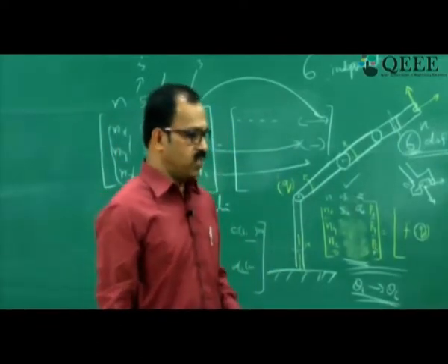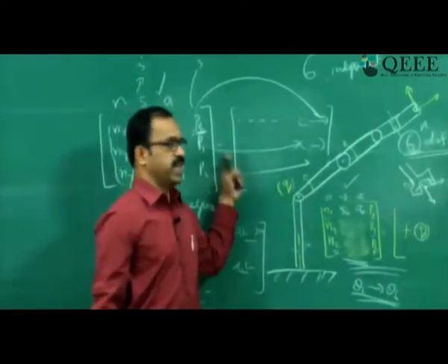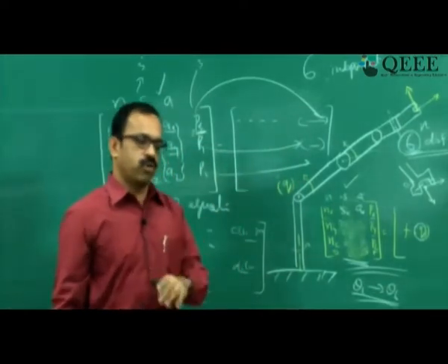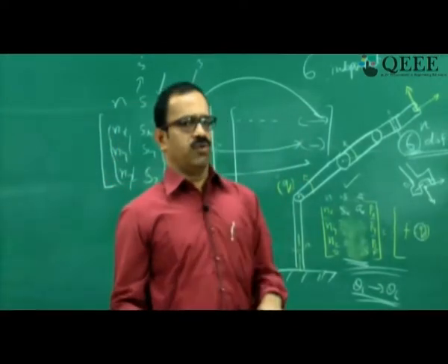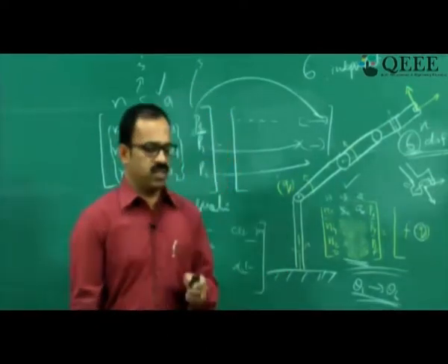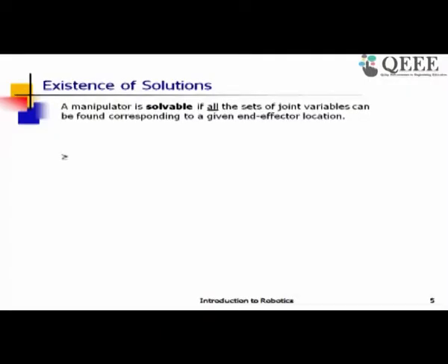But apart from this, these equations are non-linear, they are not linear equations because they are functions of theta 1, theta 1 plus theta 2 etc. and they are non-linear equations and not so easy to solve. We need to have some special methods or some ways to solve these equations depending on the type of equation that we are arriving at. And apart from this, we need to look at whether the solution will be there at all or not. So first we look at the existence of solutions, then we look at the solvability.